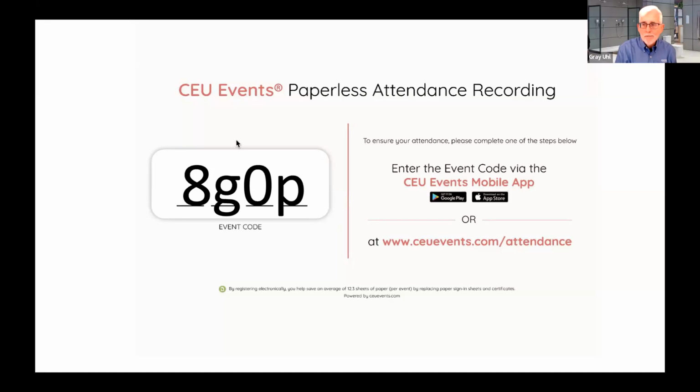Zach, you're absolutely right. If you get down below the 1.5, yeah, I think the minimum, none of them state it on the manufacturer spec sheet. No manufacturer states what the minimum flow rate is through their valve, because they're stating what their current version is testing to. But know that if you are putting on, say, a third-party valve to try to get to 1.0 or lower, which I've had requests for, you are putting yourself in a bit of a danger zone of potentially having the valve not operate properly.